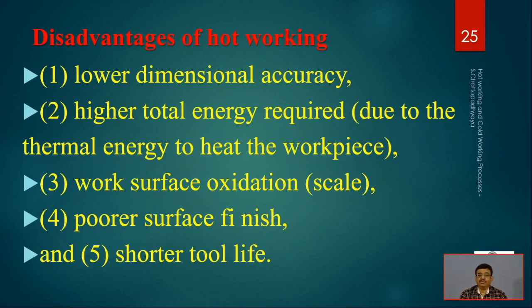Disadvantages: definitely hot working has disadvantages, otherwise all working processes would be hot ones. Lower dimensional accuracy, because of the stress relieving and recrystallization temperature. Dimensional inaccuracies will creep into the system, and that is not desirable. One has to do some post processing and be very alert about manufacturing precise products. Higher total energy is required, obviously, because the temperature is raised, and thermal energy is needed.